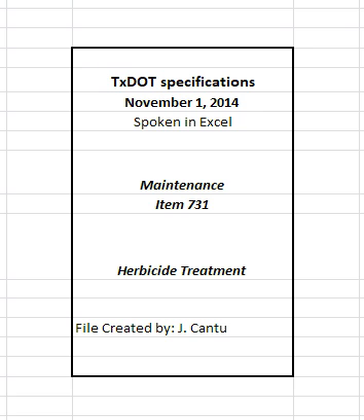Mix herbicide solution under the direct supervision of department personnel. Return any unused, department-furnished herbicide to the department. Dispose of empty containers and unused chemical mixtures in accordance with label directions and local, state, and federal regulations. Cease spraying operations immediately when wind or other environmental conditions cause off-target spray drift, leaves are wet, or rainfall is imminent.